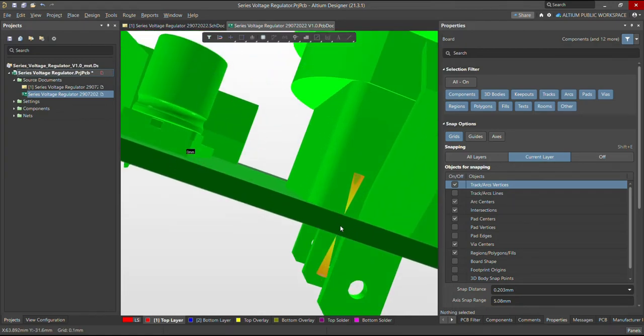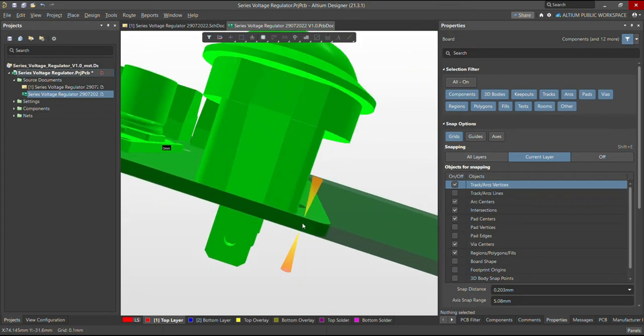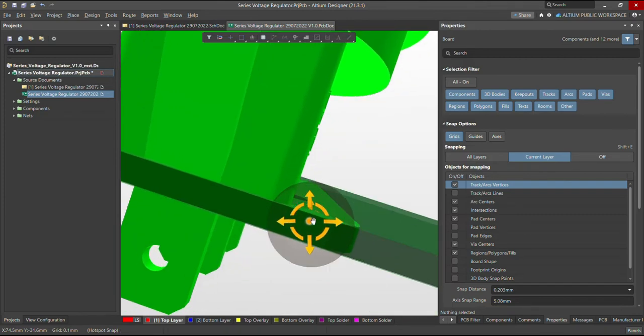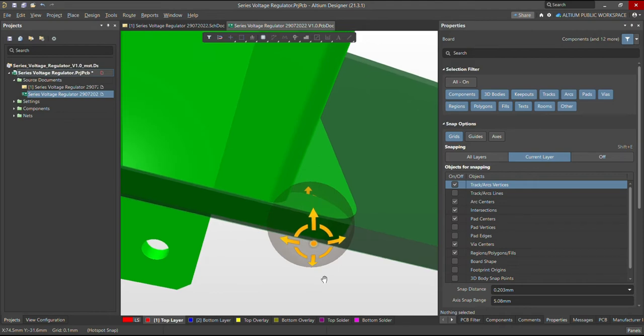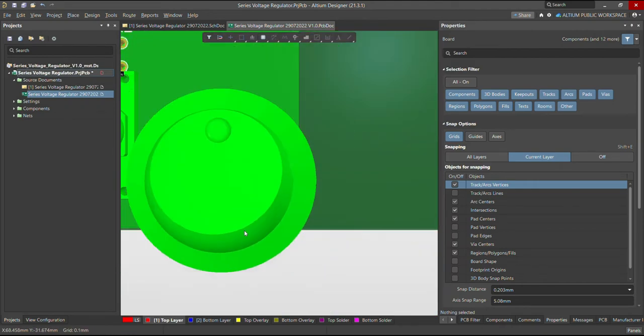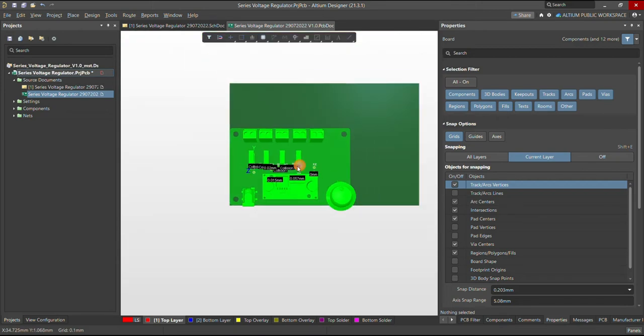So now you can see that the step data is exactly sitting on your PCB template. Okay, so now with 0, when you press the 0, it will bring you to the original position, and with V and D, it will bring you to the original size.